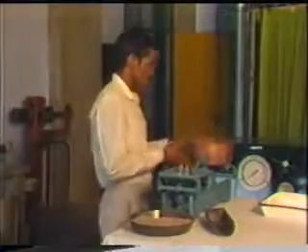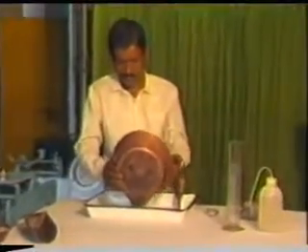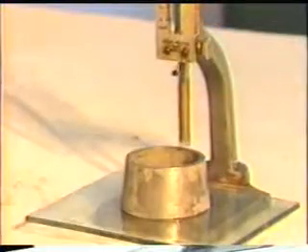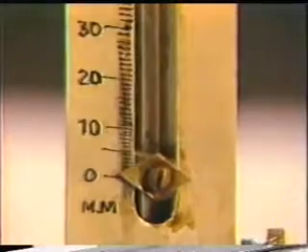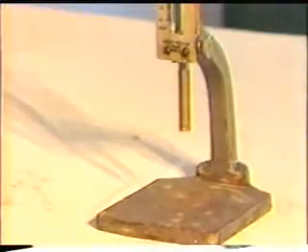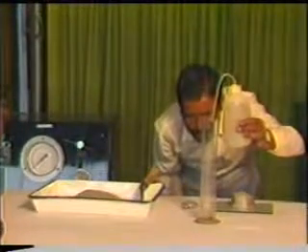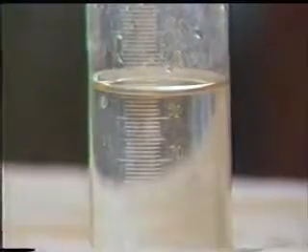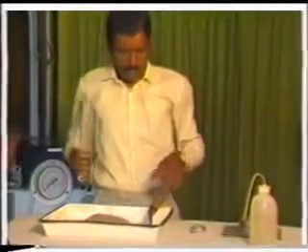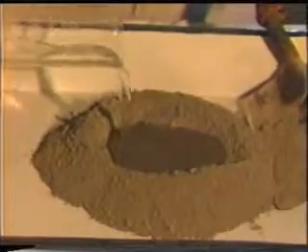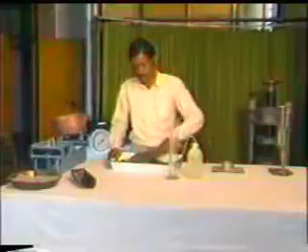Take 400 grams of cement and place it in an enamel tray. Adjust the indicator of the Vicat mold to show the zero reading when it touches the surface of the non-porous plate below. Measure 25% of clean water by weight of cement. Start the stopwatch the moment water is added. Thoroughly mix it with 400 grams of cement sample.